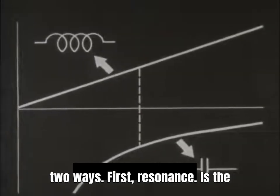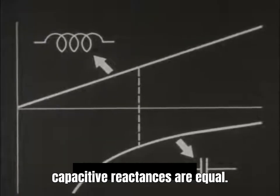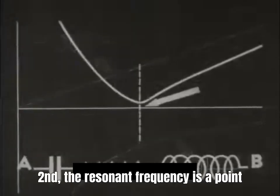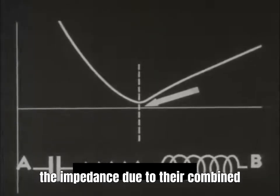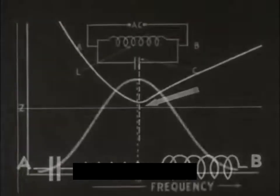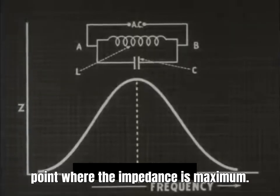First, resonance is the frequency at which inductive and capacitive reactances are equal. Second, the resonant frequency is a point in a series combination of L and C where the impedance due to their combined reactance is minimum. And in a parallel combination, it is a point where the impedance is maximum.